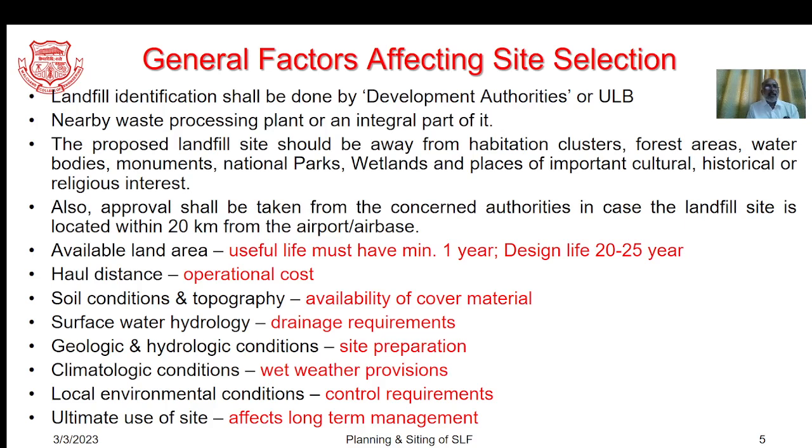Surface water hydrology is important in view of the drainage requirements. Geological and hydrological conditions are also important because various cells need to be resting on the bed that we wish to prepare. So the leachate as well as the settlement and such aspects need to be studied.